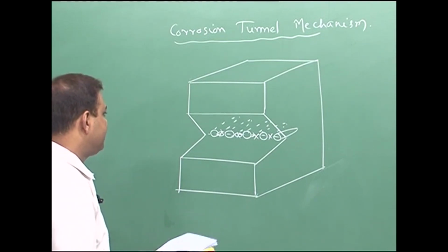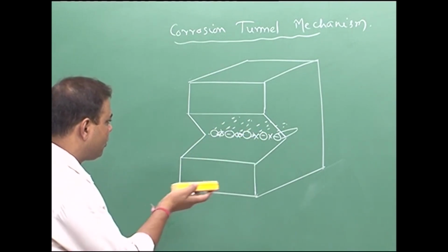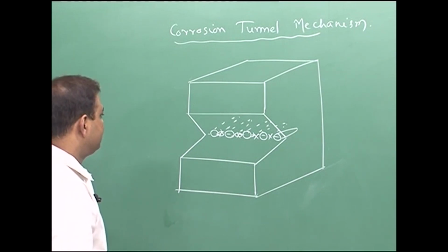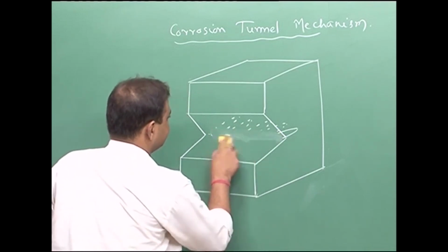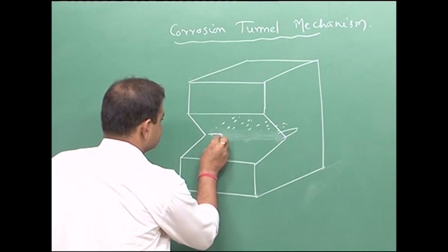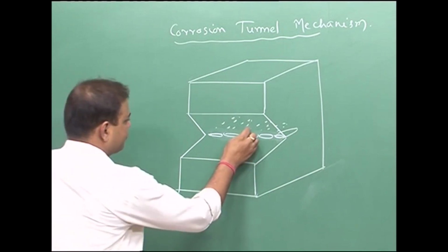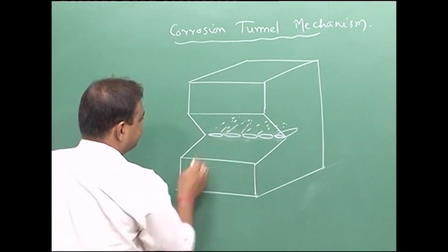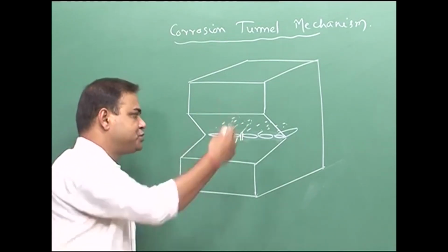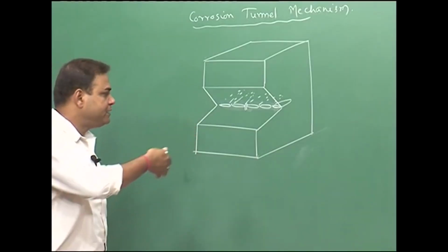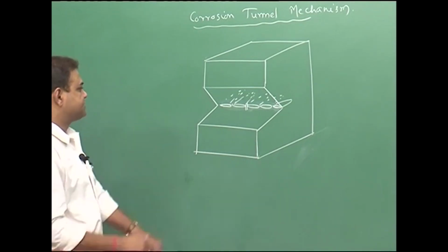The modification says that the same micro voids, these tunnels, form on the zone of slip steps, then instead of growing laterally and uniformly, they form slots, and those slots grow inside the material. And finally the dimension might reach atomic dimension, and there could be a complete match between the two fracture surfaces.